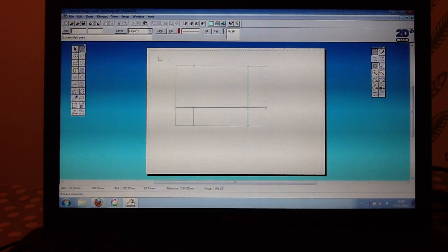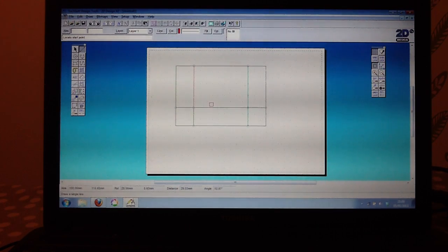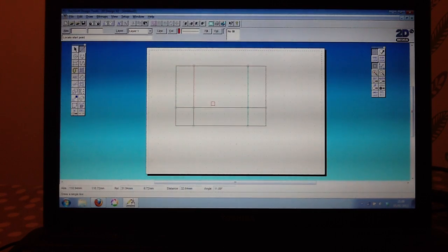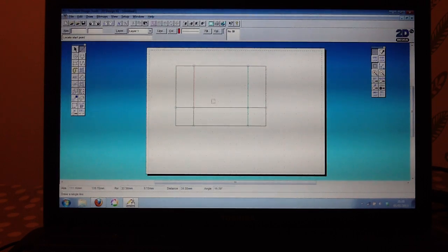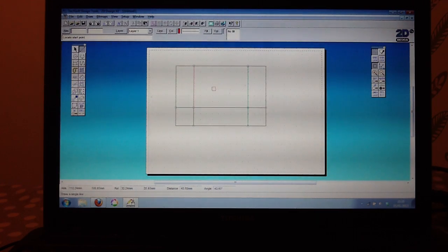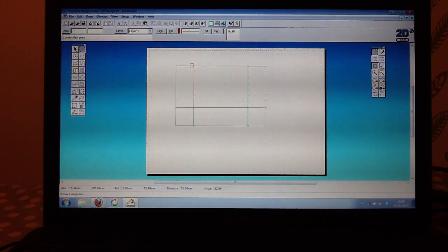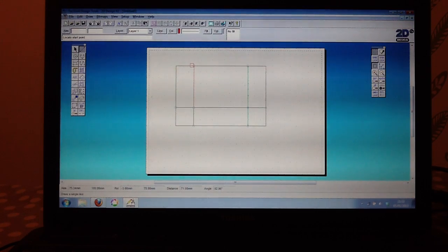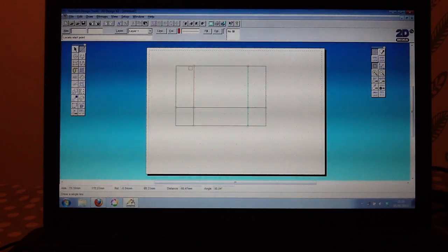go back onto the line, still with the touch on, we can change the colour of that line but still snap to the construction point, so we're not trying to guess where our line should be or if it's going to be accurate. This is particularly useful when you are using an output such as a laser cutter, because obviously some lines need to be one colour for engraving or creasing, and some lines want to be another colour for cutting.